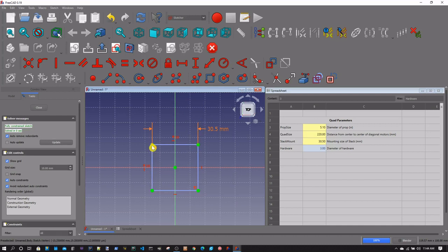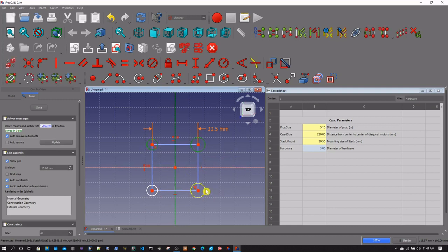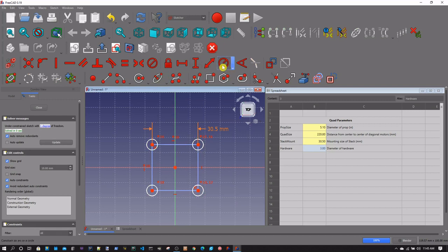So the next thing I want to do is lay out the actual holes, because this is what the square was for, the holes of our stack. So I'm going to return my sketching tools to regular, and I'm going to add a circle to each one of these points here, making sure I get that coincident constraint, the center of the circles. And then I'm going to make all of these equal. We'll select them all. And you can either press the E key, or you can come up here to the equals constraint. Oop. Missed them there. You misclick it, clears them all. So we'll select the equals constraint. And then we're going to come here. This is our constraint radius. We're going to hit the drop down and constrain diameter.